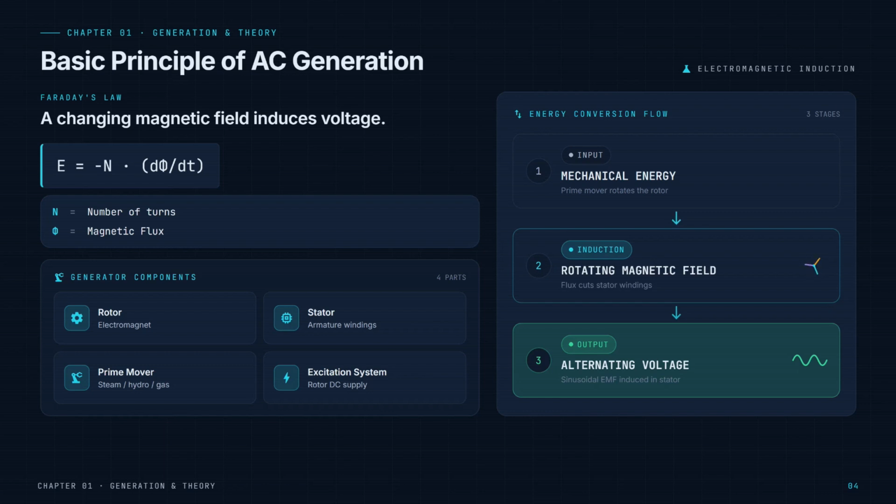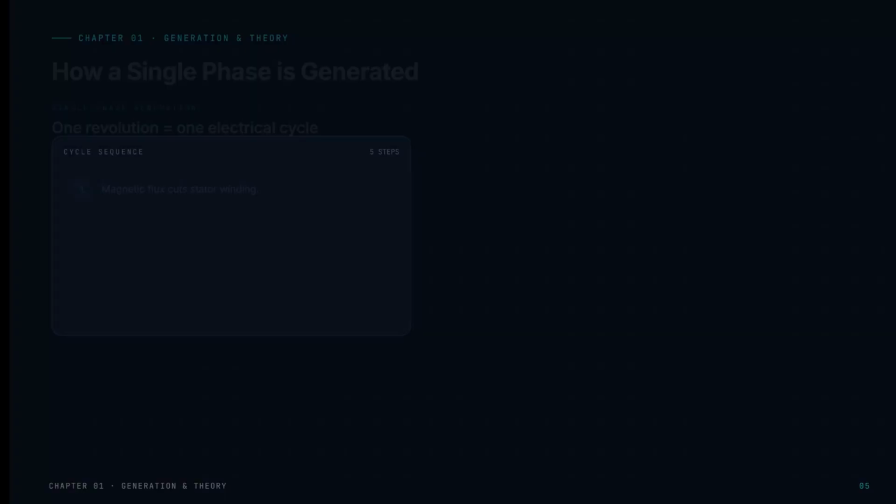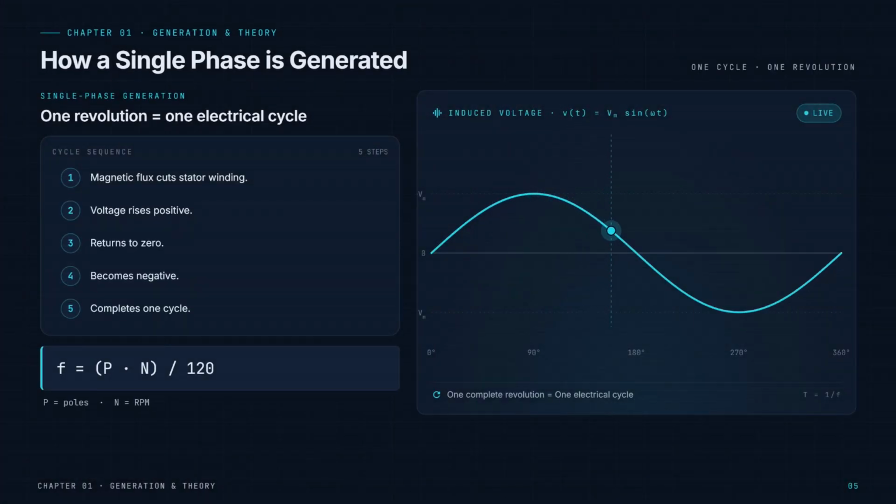Electrical energy begins its journey at a generating station where mechanical energy is converted into electrical energy using the principle of electromagnetic induction. A turbine driven by steam, natural gas, water, wind, or nuclear energy rotates the rotor of a synchronous generator. As the magnetic field rotates past stationary windings inside the stator, an alternating voltage is induced.